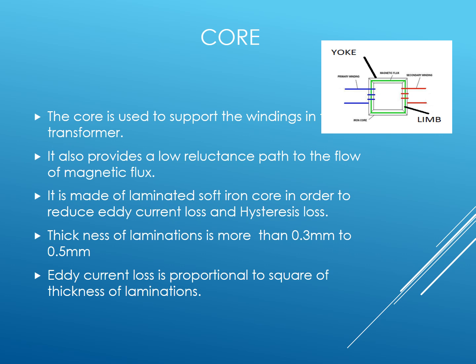But some of the alternating flux from primary to secondary of the transformer may also link other conducting parts instead of linking with the secondary winding, other conducting paths like the steel or iron core of the transformer. Those fluxes are called leakage flux.